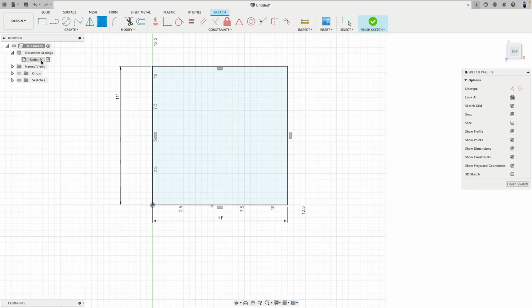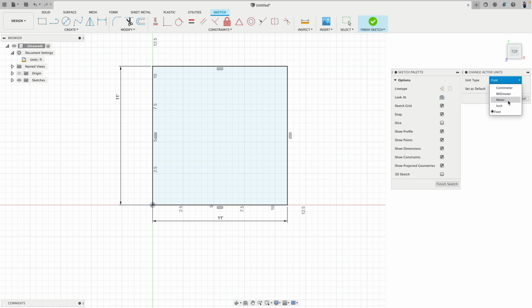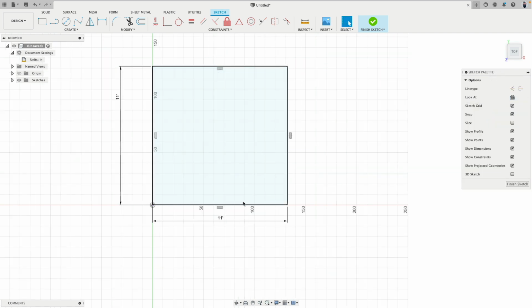Cool. Okay. So you see, it doesn't actually matter much. It's really based on how you want to work. I will set this to inches. The display, however, is to architectural. So I can always type in 11 feet. Or I type, for example, in 2 inches. Or 2 just because it's inches. Anyway, so the interior dimension of the room is done.